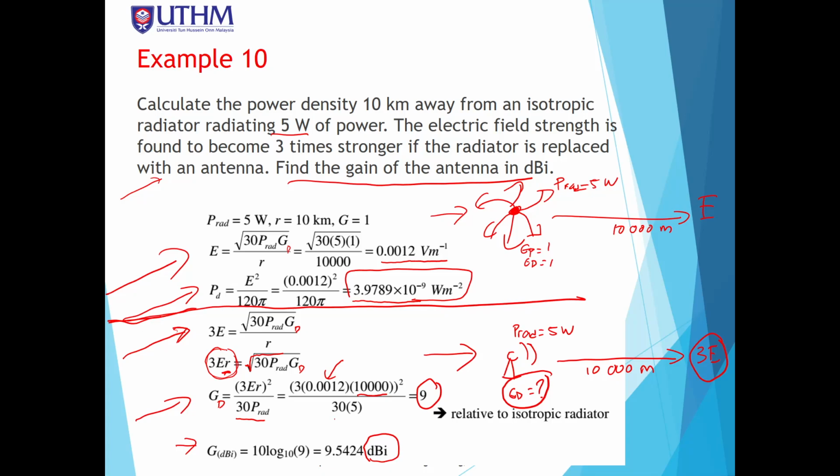Normally for the antenna gain, we use dBi. So when you buy an electronic device at the shop and you see the specification of the gain, especially if you buy a device that contains an antenna, for example a wireless router, and you read the specifications of the antenna, you're going to see a decibel, a dBi.